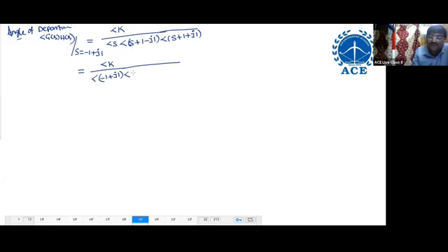Minus 1 plus j1 means 0. Here substitute minus 1 plus j1, minus 1 plus 1 cancel. That means plus j2. You should be perfect in the calculations of angle of departure, angle of arrival and breakpoints. It is simple substitution only. Substitute and get the answer. Angle of K is 0 degrees.